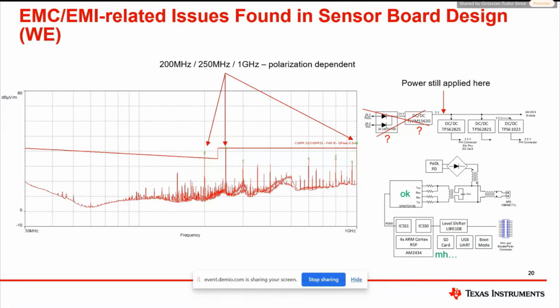Also, let's check the datasheet. The AM6442 MCU outputs a clock with a rise time of around 1 nanosecond. Checking the layout, we found out that it was not actually designed for this, and this very fast rise time was not accounted for when doing the layout. Also, there was some poor ground plane use around the SD card, and on the SD card there were no series termination resistors, and this could cause the high frequency communication between the microcontroller and the SD card to radiate.